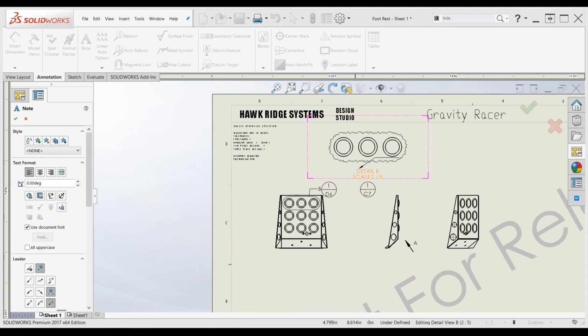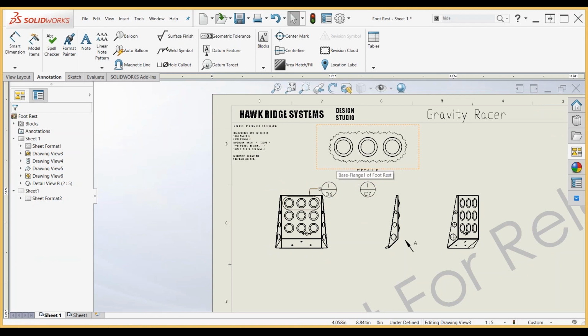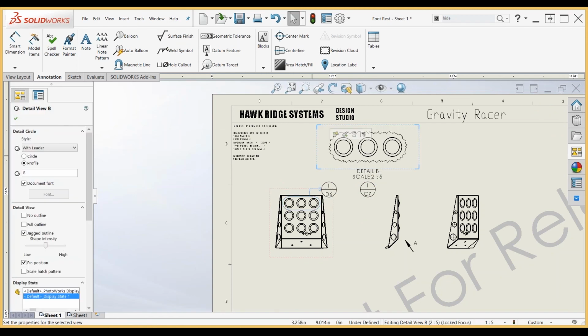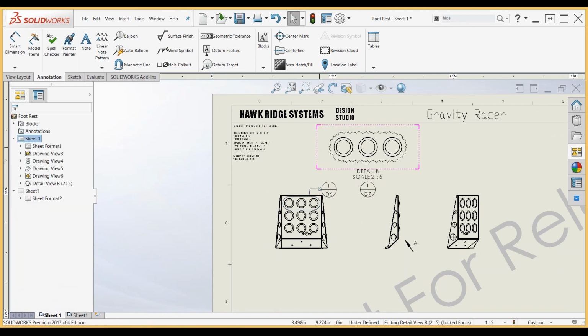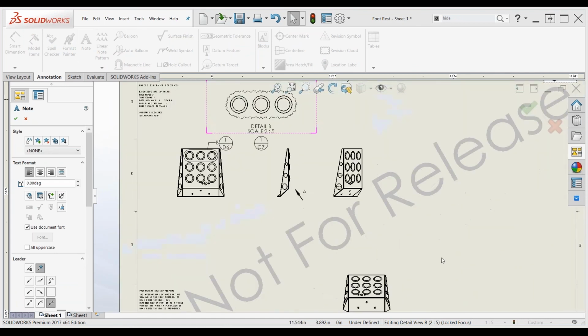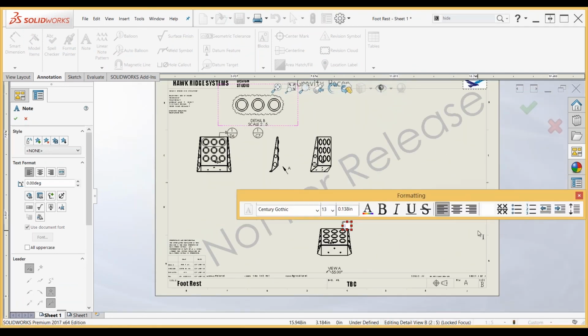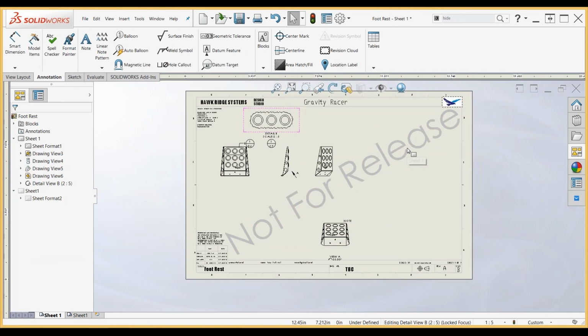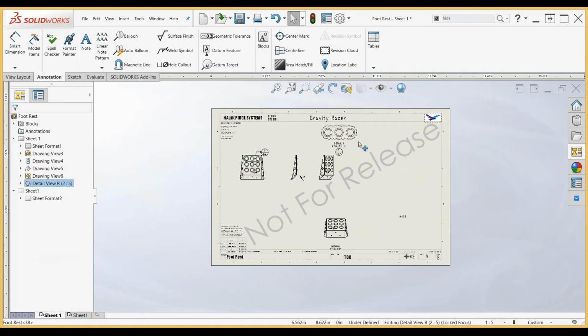So on this second sheet here, I want to pull in my flat pattern. And with my flat pattern, I want to export it as a DXF so I can get it cut. So I'm going to hide my bend notes because I don't want to see those. And I want my scale to be 1:1. So I'm going to change my sheet scale here to 1:1, but we can see that, okay, this is way too big. It's not lining up with my sheet. The sheet's too small.